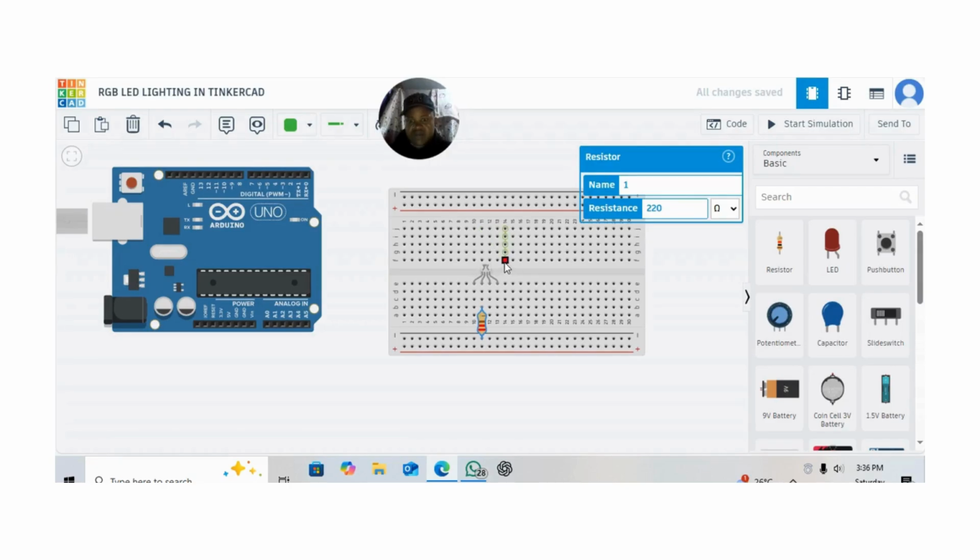So if we are using another component, in which we are giving an input to our Arduino here, we could have used these analog pins at the bottom. For example, if we are using a potentiometer, you would have connected it into these ports here, and the same thing applies to other sensors, maybe the PIR and many others.